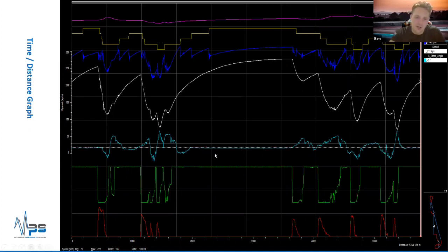Whereas if you're looking at driver data, I often find for nearly every case you're trying to consider, you're much better to look at your data with respect to distance, and that's distance around the lap. So I've got a bit of data up here from the Paul Ricard circuit I've just come back from. The reason we do that is because generally speaking, there are exceptions here, but generally speaking, turn 1 at Paul Ricard will always occur at, I don't know, 540 meters into the lap.